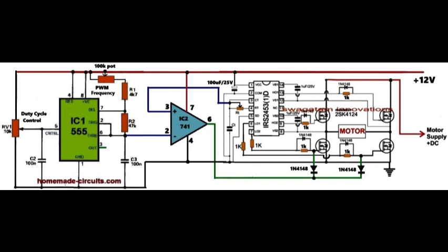The SPWM Generator section. To transform the square wave into a sine wave equivalent, an adjustable SPWM, or sinusoidal pulse width modulation signal, is generated and integrated into the H-bridge. The IC555, configured as an astable multivibrator, generates a fast triangle wave which acts like the carrier wave. This carrier wave is fed to the non-inverting input of the comparator IC741.